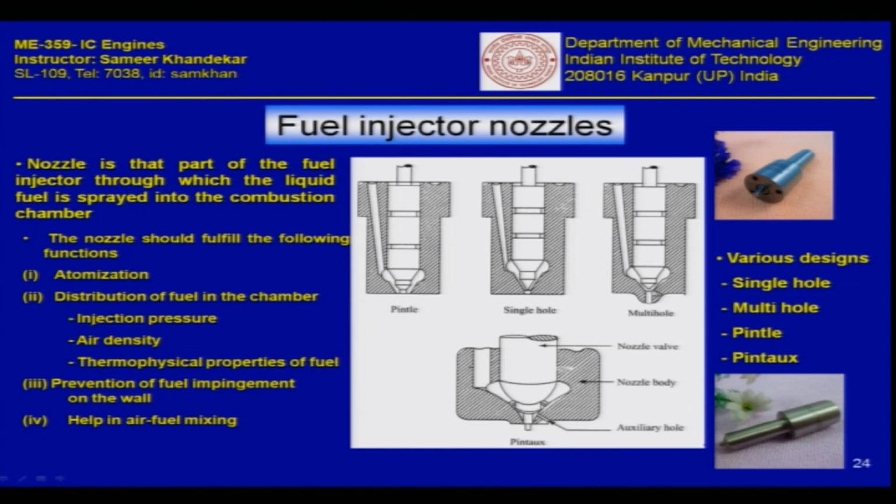Now, depending on the angle at which you have this multi nozzle, for example, this will spray in various directions, okay, and depending on how the combustion chamber is designed, we would like the fuel to be properly distributed in the combustion chamber, so that the combustion efficiency increases, okay. And this distribution will depend on the injection pressure, it will depend on the air density and also the thermophysical properties of the fuel.